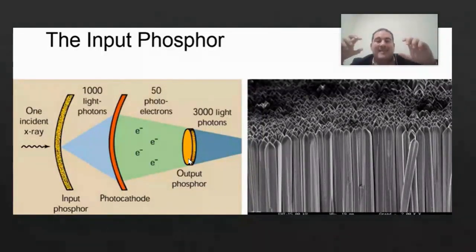You want to increase the resolution a bit. How to increase the resolution then? By adjusting the voltage values that affect the electrons generated by the photocathode, you can achieve better focusing and reduce the diameter of that area or region. In this case, it's as if you are increasing the resolution of the image, but it will come at the expense of the number of light photons that you were originally producing, which decreases. Therefore, the magnification here